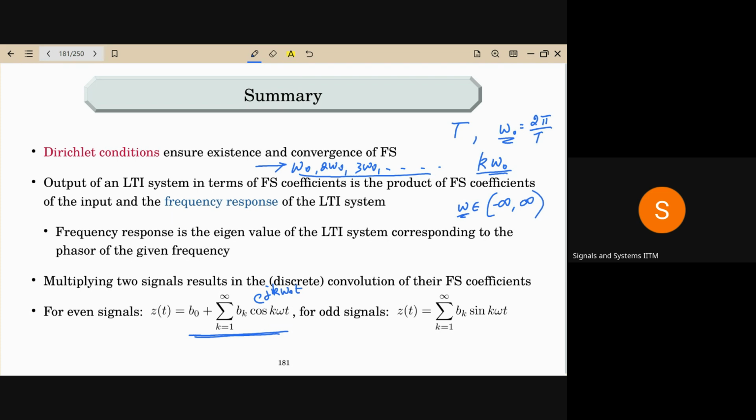Because Dirac delta representations are messy, we use Fourier series. Otherwise, we don't need Fourier series at all. Fourier transform is sufficient to represent the frequency components of both periodic and aperiodic signals. The only issue is that because of Dirac deltas, we still use Fourier series. Otherwise, you don't need to know Fourier series at all. If you are comfortable using Dirac deltas, then you can completely forget about Fourier series.